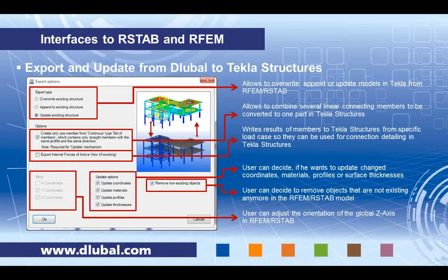On this main girder you have additional cross beams that connect somewhere along this main girder as secondary girders. And when I analyze it inside Dlubal software or typical all other software, then you have to make a connecting node where those intersection points are. So inside you have actually 3 analytical members maybe where there is only one major part in Tekla Structures.